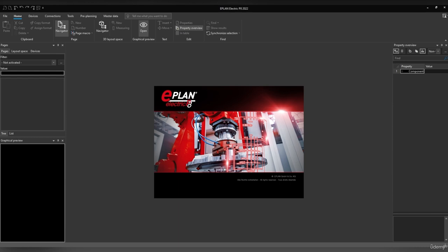The fifth one is the .elx, a filed off and zipped project. The sixth one is the .elr, a completed project, so completed and sent to the customer. The seventh and last one is the .elt, a temporary EPLAN reference project, so we do a lot of comparison in that project. All other types of project are derived from the normal EPLAN project, the schematic project.